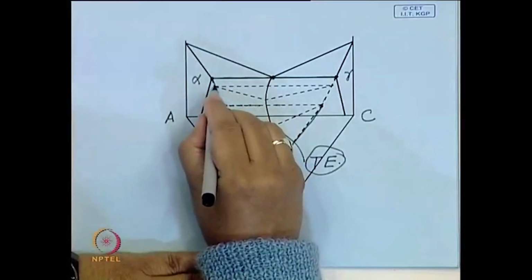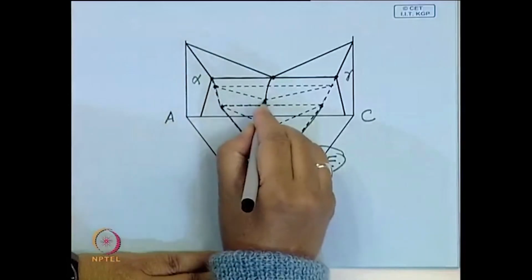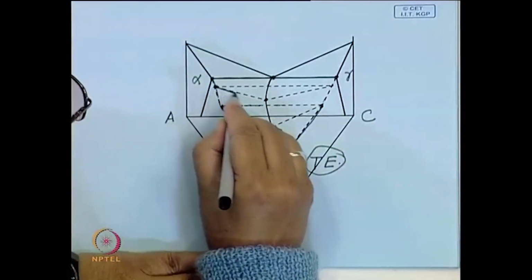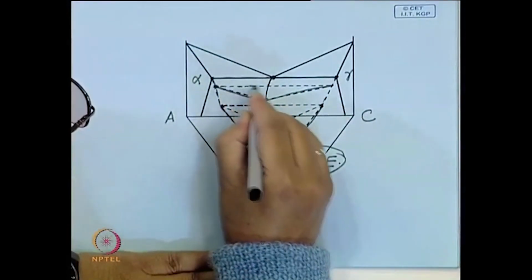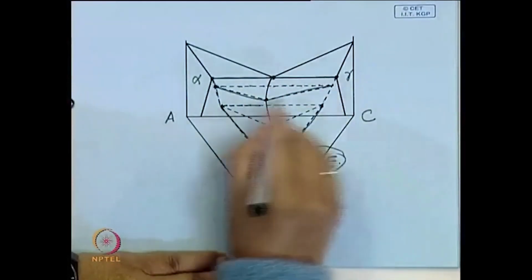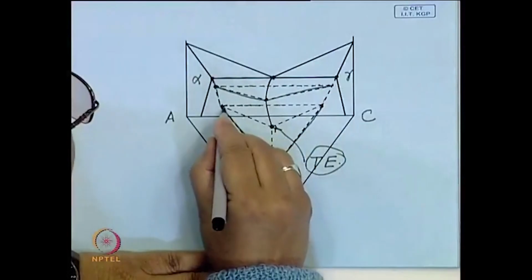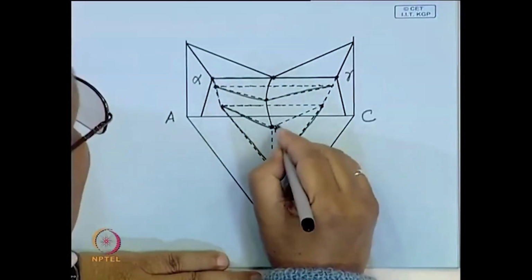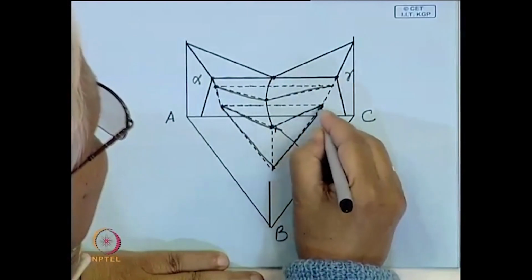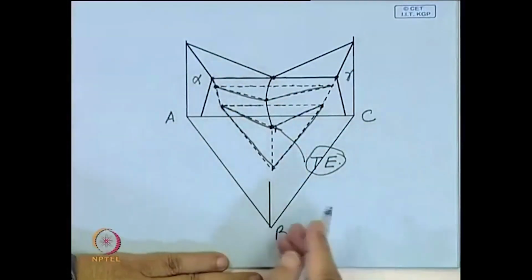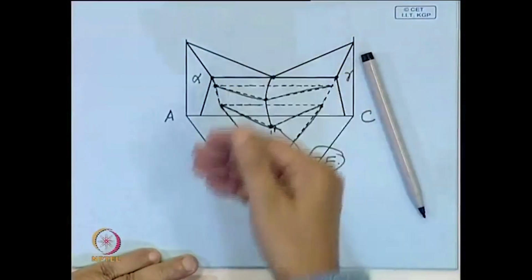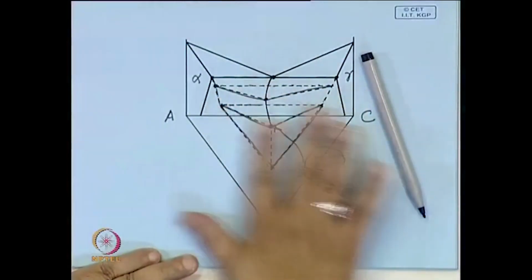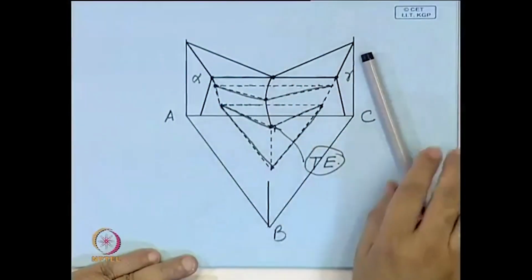Now you see, what you generate here is one isotherm, one point intersecting here, so this kind of triangular region, and these are the dotted lines which are behind. Similarly, this is another point where it just meets the eutectic isotherm. So, this type of triangular plane just comes down and meets the ternary eutectic isotherm.